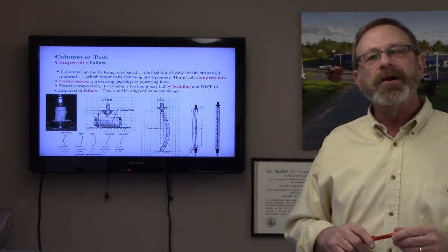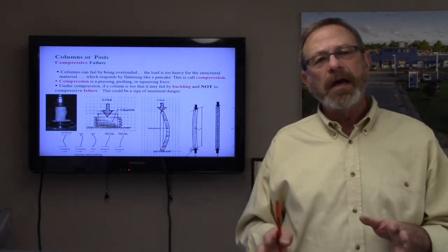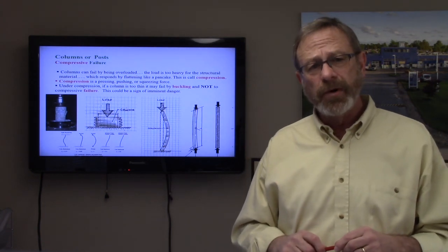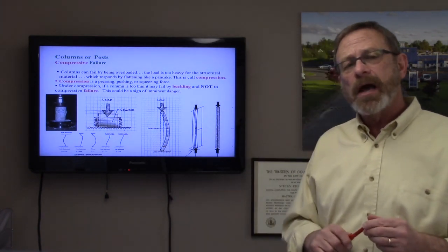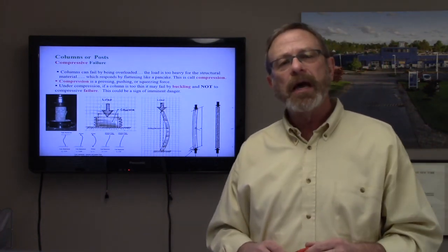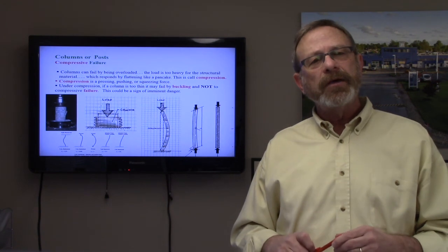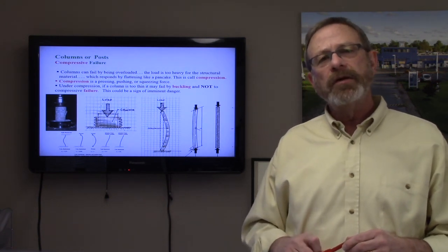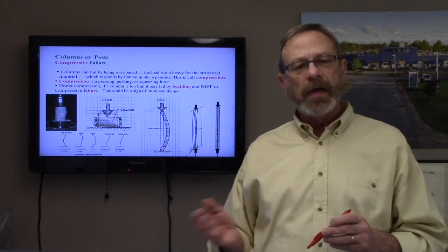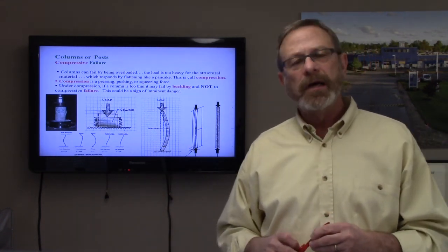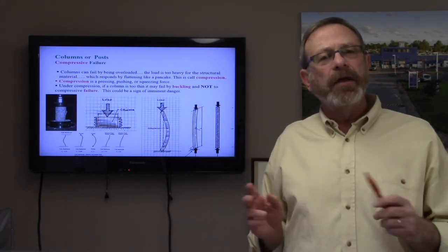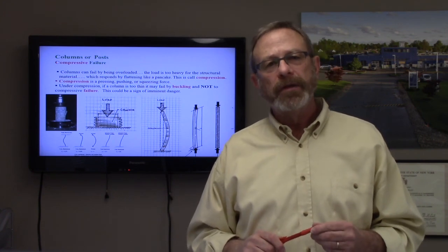Sometimes an unscrupulous contractor will add water to cheapen the concrete. Of course, with more water, it's not going to achieve its expected strength. So we do check concrete while it's being poured on a job in little cores by an independent contractor who takes them to the lab and tests them for conformity with what the engineer specified. If it doesn't meet expectation, then there's every right of the owner to have that contractor remove all of the concrete on the job for failure to meet specification and then failure to be able to perform in the expected manner.